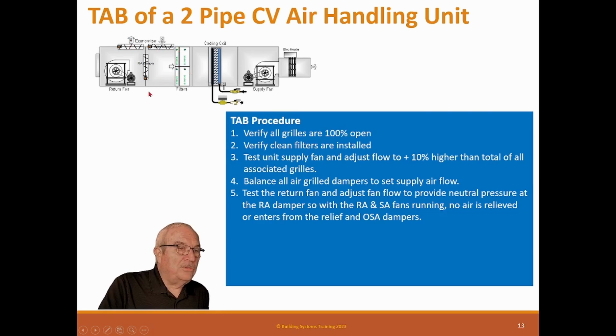So what you do is you balance this system so there's a neutral pressure right here. So this fan is just doing what it needs to get the air through this damper. So it's taking this air through that and it's placing it there. This should be 0. So this fan should be inducing the negative pressure. This fan should be inducing the positive pressure that's required here.